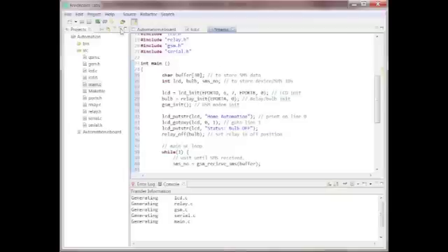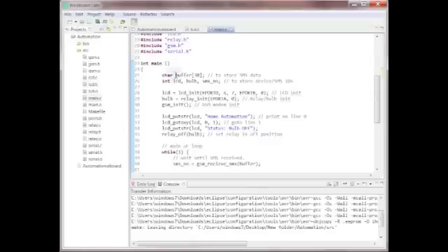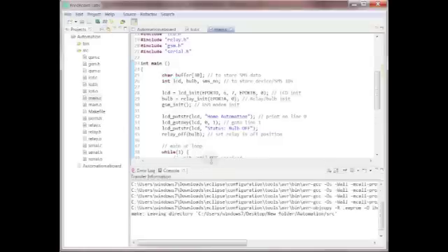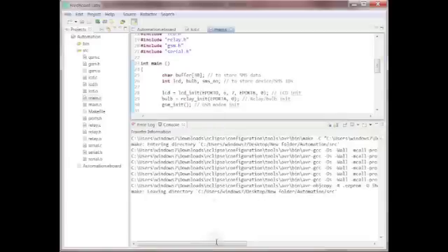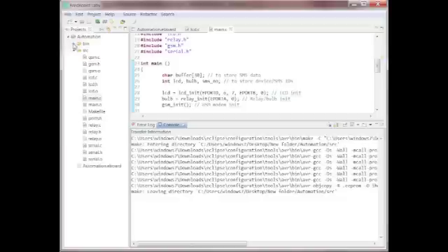Ensure that you save this file now. To compile the code, you simply click on the toolbar button here, like this. Wait for a few seconds, and wow! You just compiled your project and it's ready to be executed on the real board. The compiled executable is a hex file that gets generated in the bin folder, here.